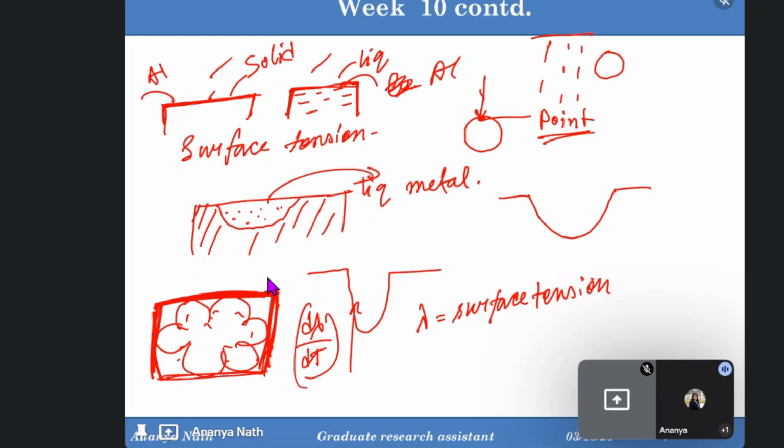It can be on the negative side or the positive side, it doesn't matter, but it will be very high, and due to that the solidification will not take place properly. So if you are going for casting, you have to choose the mold material accordingly.